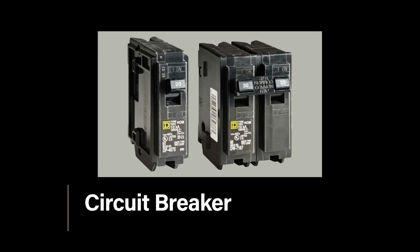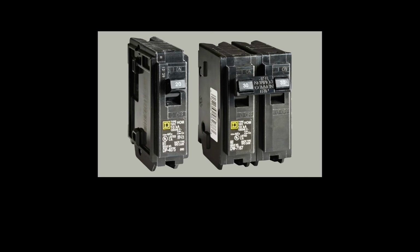Circuit breaker. This is commonly found in electrical panels of homes and, similar to fuses, acts as a switch to turn off the power if it detects a higher current than expected. A circuit breaker can be reset to the armed position after being disarmed. However, it is expected the reason the circuit breaker disarmed should be investigated and the necessary electrical solution must be taken care of before resetting the breaker to the armed position.